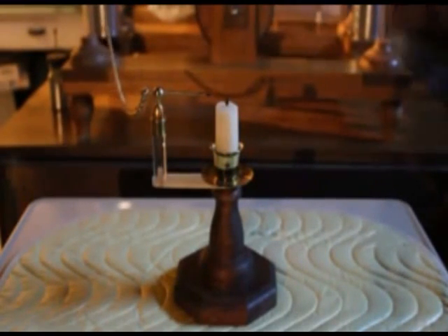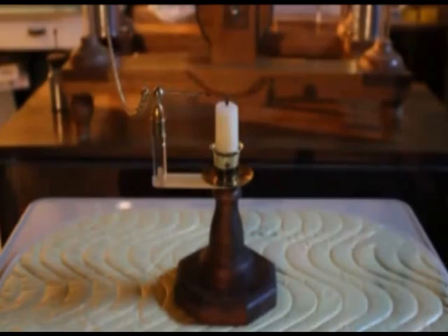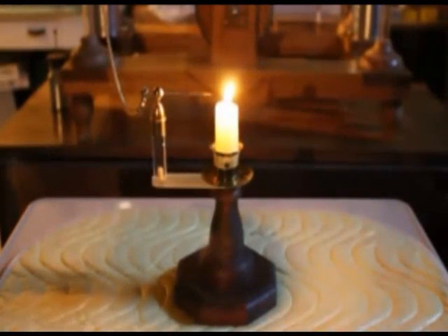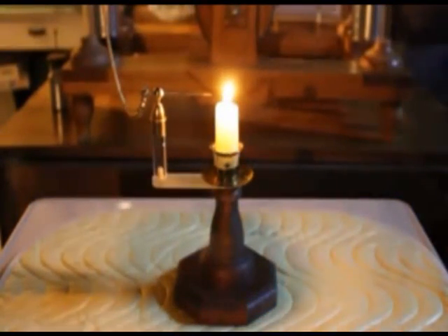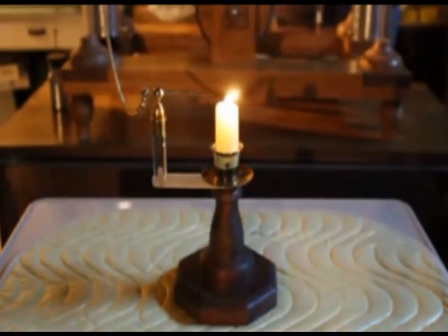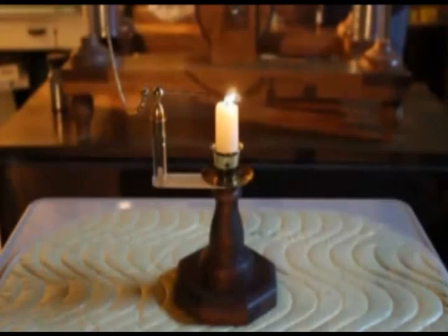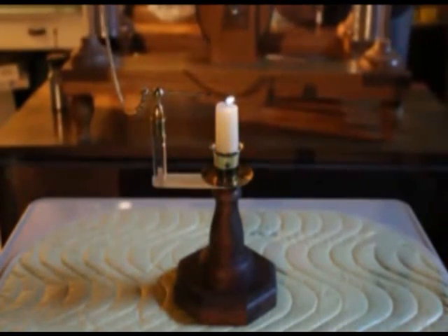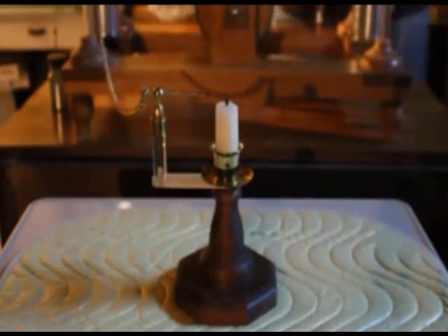If the charge on the wire is positive, the high concentration of positive charges at the sharp point of the wire causes ionization of the surrounding air to produce electrons and positive ions. Electrons in air are attracted towards the positive conductor, while the heavy positive ions drift towards the flame, forming an electric wind.